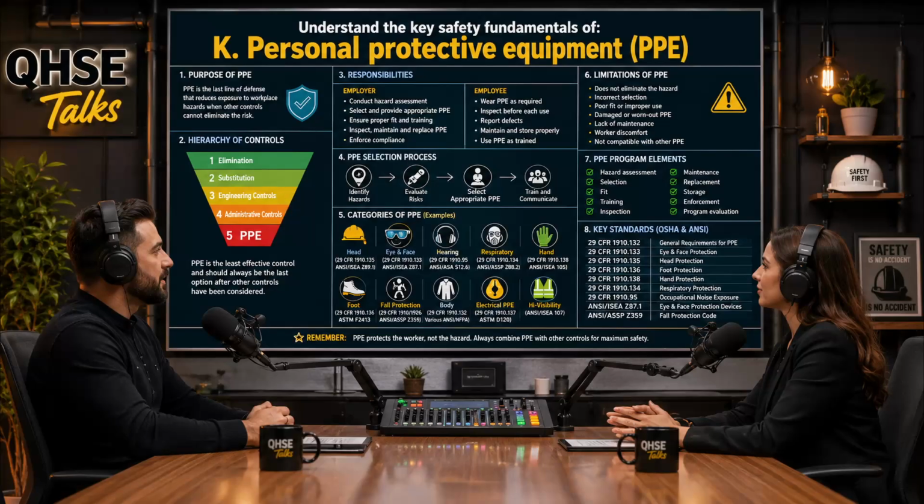You also must understand the physics of how a hard hat actually works, right? Because it is not just a hard shell bouncing an object away. No, the shell is just the first part. The critical component is actually the internal suspension system, that webbed harness that sits on the worker's skull. How does that work during an impact? When a 10-pound object strikes the shell, the kinetic energy is transferred into that suspension system, which stretches and elongates. This distributes the localized force of the impact over a massive surface area and significantly slows the deceleration curve.